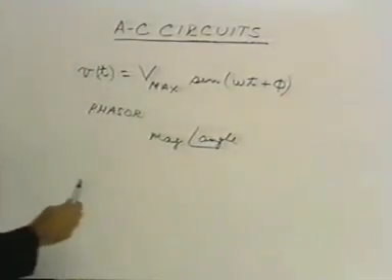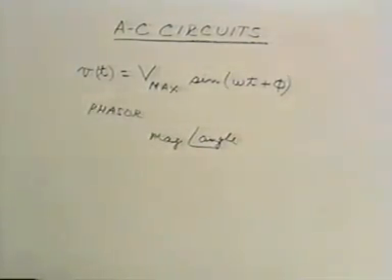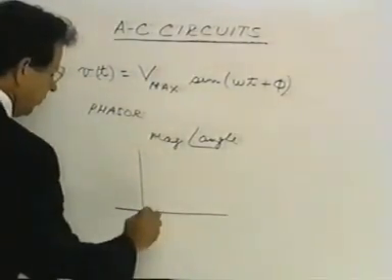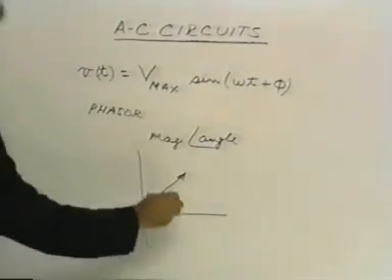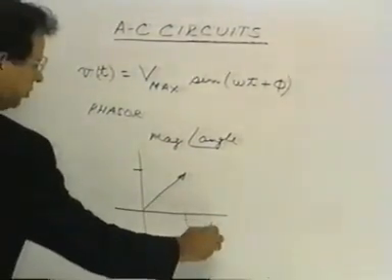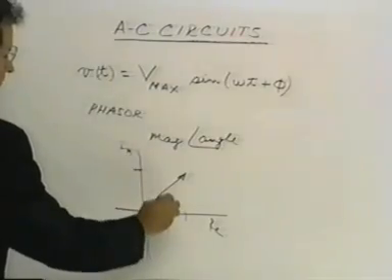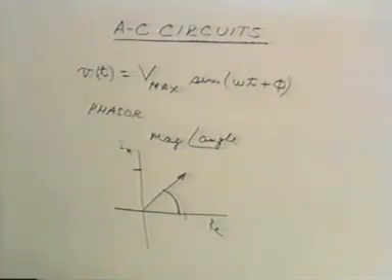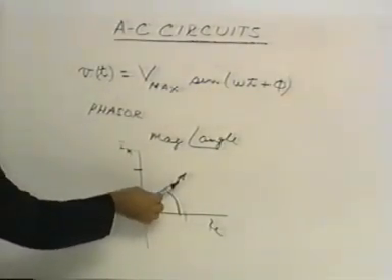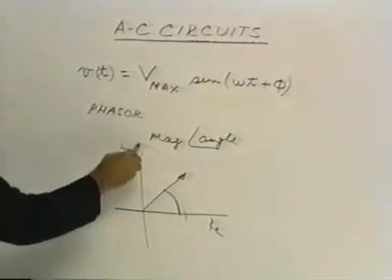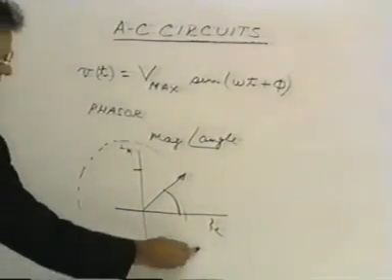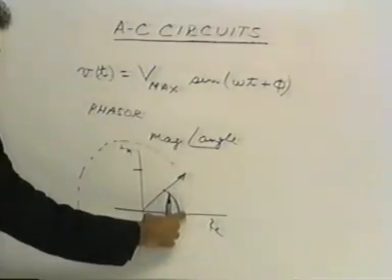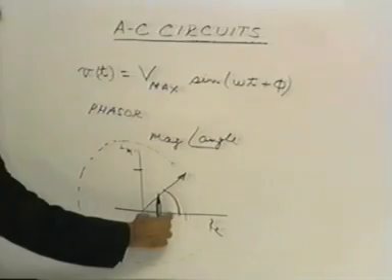Now imagine that time were standing still. If it were, the voltage can be shown as a complex number that has a real part and an imaginary part, and it forms some angle with respect to the reference axis. Notice that if we let the clock start to run now, and this vector continues to move counterclockwise like this, as it does that, the projection onto the real axis will shrink and go to 0.